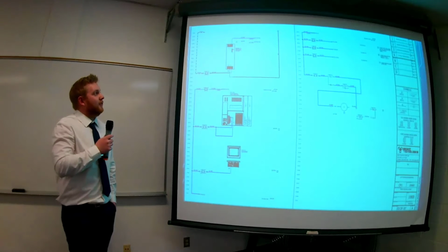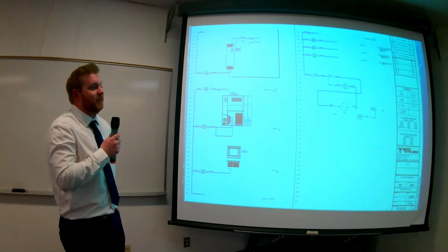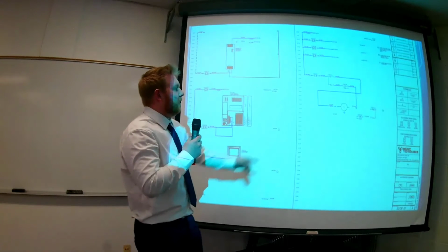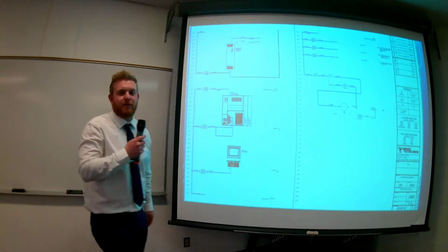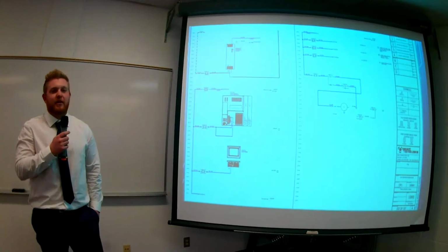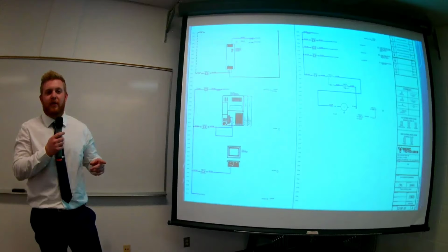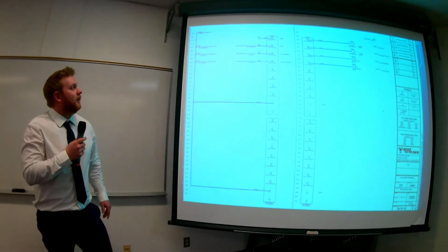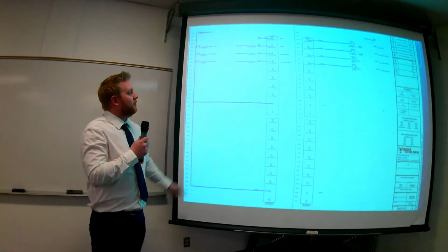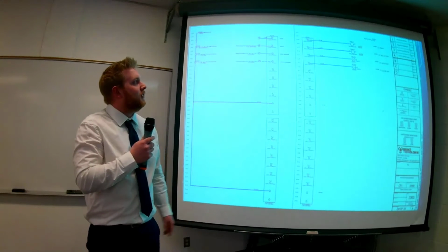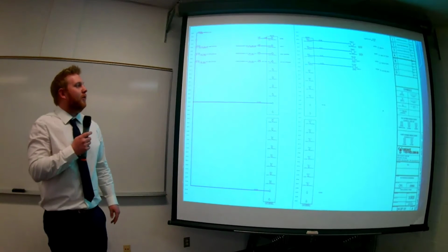And then the electrical drawings, which you probably can't see, but one of the biggest things was that our motor has to go forward and reverse but only has 2 leads, so we had to put in 2 relays, a forward and a reverse relay, so they could not be forward and in reverse at the same time. You can hit next. And then this is just our IO drawings. You can see our 2 lights and our relays that are outputs, digital outputs.